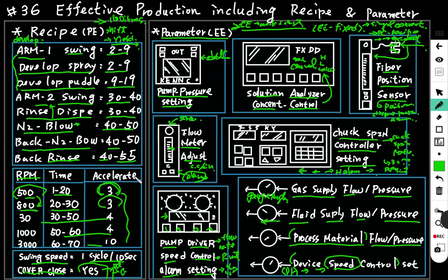So a superior advanced equipment is designed to transfer all the set item values to the computer of the factory, and every time it runs for production, the factory computer reviews all the item values. If one has shifted, the computer will not let the equipment run the production wafer and gives a warning to let the engineer check it out.